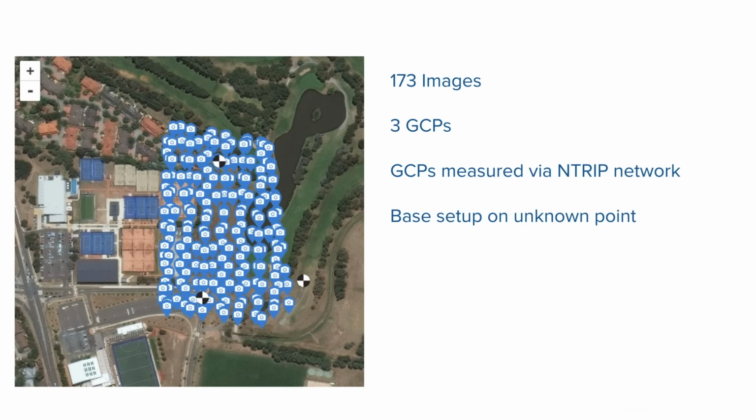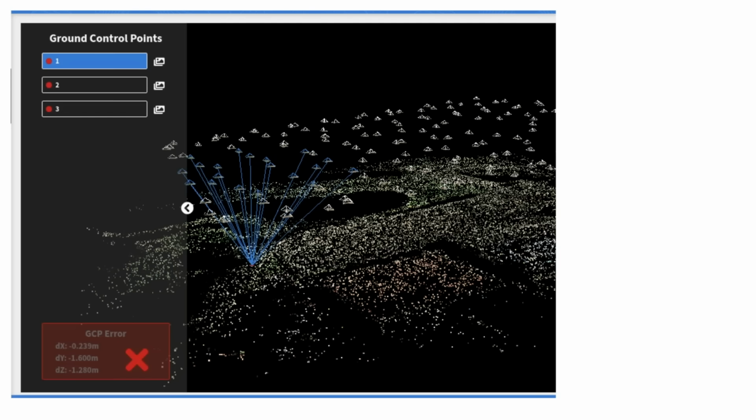Okay, so before we introduced any ground control points, all of the photo positions were, like I mentioned a couple minutes ago, all within plus or minus 5 centimeters of the photo position that was given in the log file. Okay, but then what we found out is that when we added the ground control points, so we brought in these 3 ground control points, we were like, what is going on here? Why do my ground control points have an error of up to 1.5 meters?